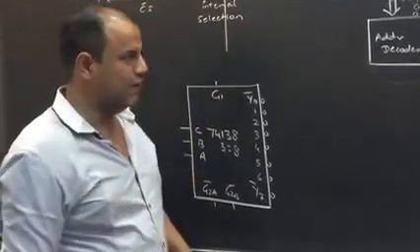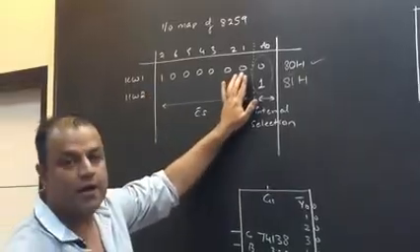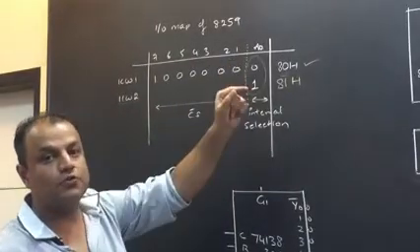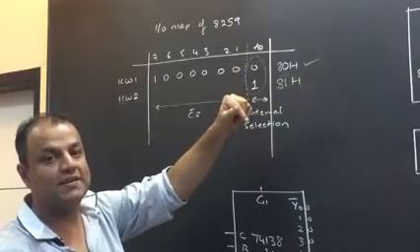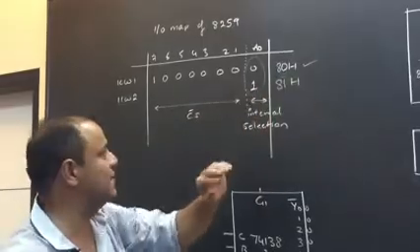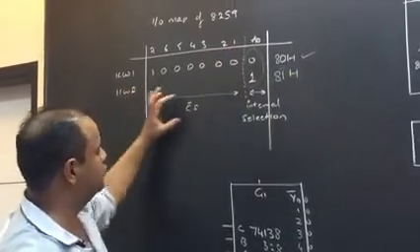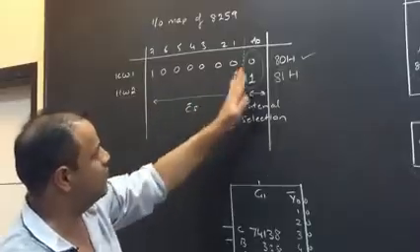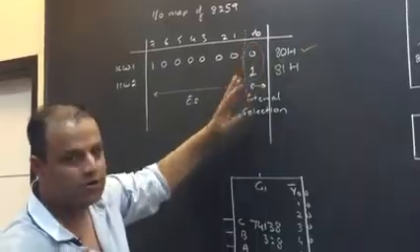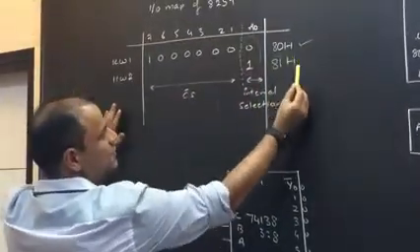We again use the decoder. The decoder will put conditions on A7 to A1. Did you understand why I have kept A0 free? Because A0 has gone inside the chip to decide whether it's ICW1 or ICW2. Whether it's ICW1 or ICW2, it belongs to the same chip. So A0 is used for internal selection. This part is used for chip selection. This part has to remain constant. A0 can be any value. That means our decoder will not put any condition on A0. I'll say for the last time, the decoder should select the chip for the address 80 and 81.